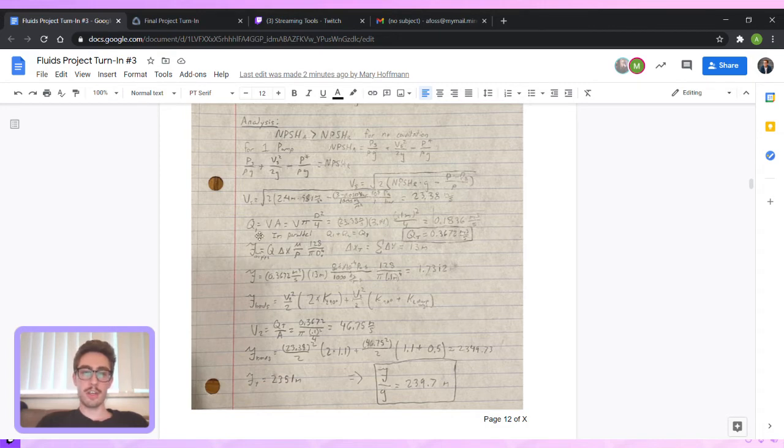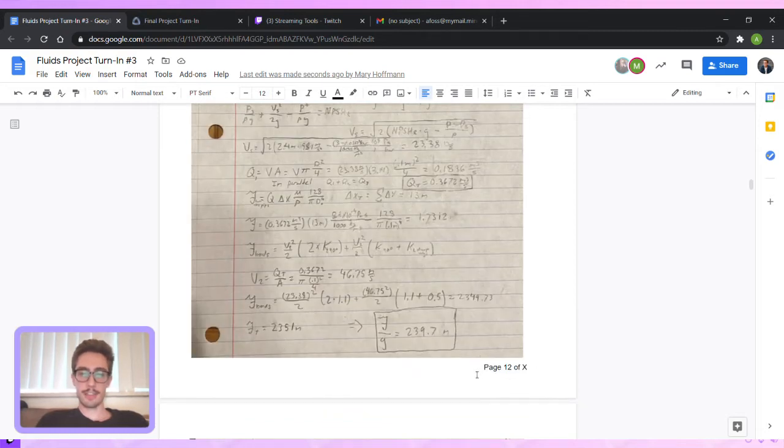After this is done, we can determine the frictional loss due to the lengths of these pipes by using the frictional loss equation for laminar circular pipes. Once this is done, the frictional loss for the bends in the pipes is found next. And so these frictional losses are combined, and therefore we can find our frictional head loss.